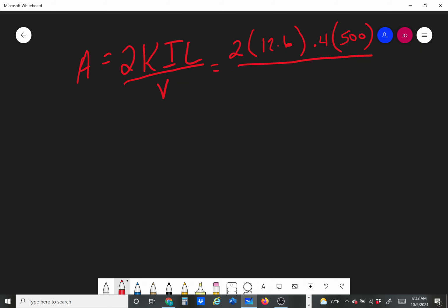Now, where this question gets a little bit dicey, it tells us that the manufacturer has given us a plus or minus 1 volt. Normally, I would take my 12 volts and multiply it by 3% and see that I could drop 0.36. I could only drop 0.36 volts by the code recommendation. But the manufacturer says I can actually drop 1 full volt. So this will work as low as 11 volts. So since the manufacturer told me that I can drop 1 full volt, that is going to be my maximum voltage drop. It says it right there in the question.